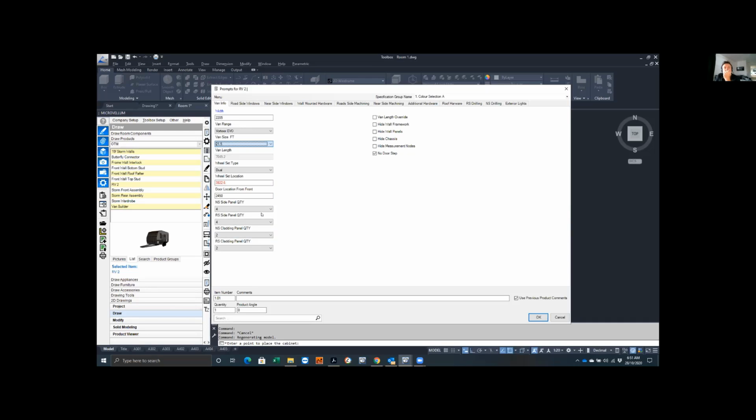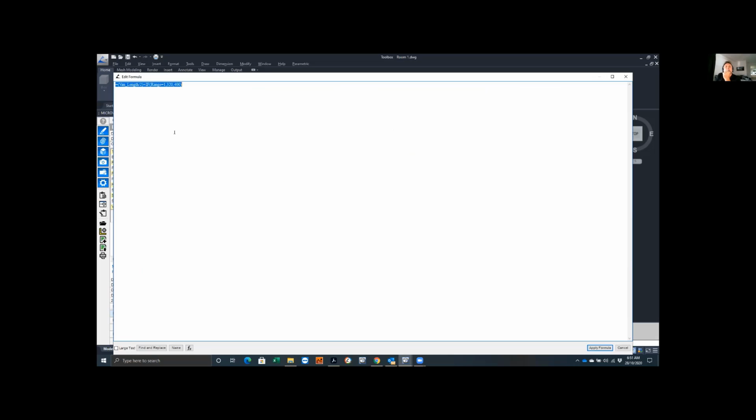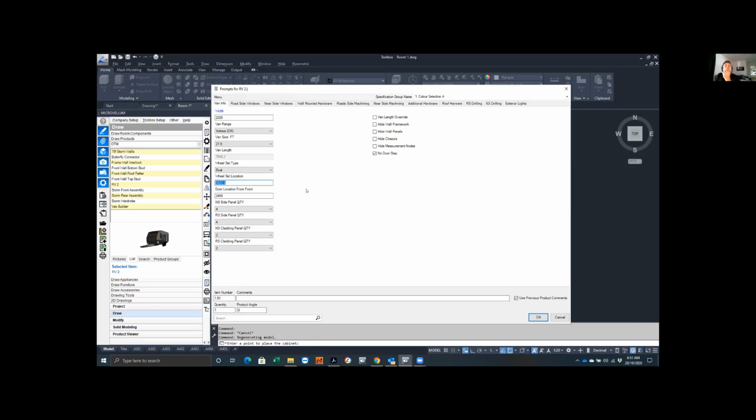It must be because old people typically have RVs, so they like feet. So if I want a 21.5 foot van, I have that there. It calculates the length of the van depending on the range. It'll automatically select how many wheels it needs. So it's got a dual wheel set on it. The wheel set location is also automated as a formula. So depending on the range, it'll move the wheel set forward and backwards.